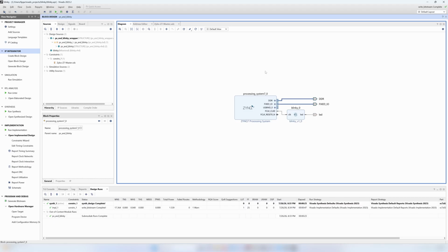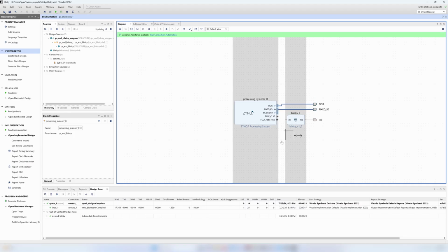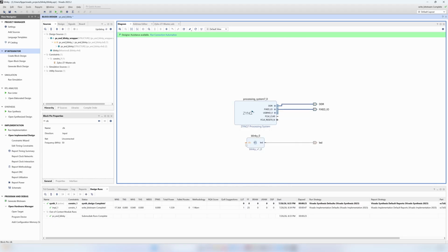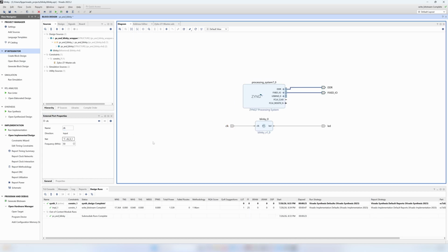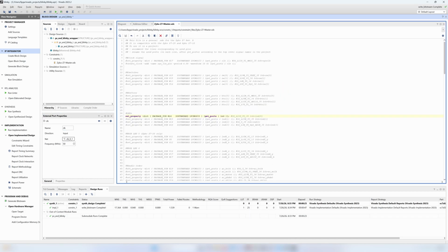And so that can be a somewhat tedious process of going through the whole Vitis setup every time you want to test a simple HDL. And so if you're doing an initial testing of integrating the processing system and a piece of HDL code, I'll usually not do this and do what I did in the first video, which is make this external and connect it up to the clock on the circuit board using the constraint files.